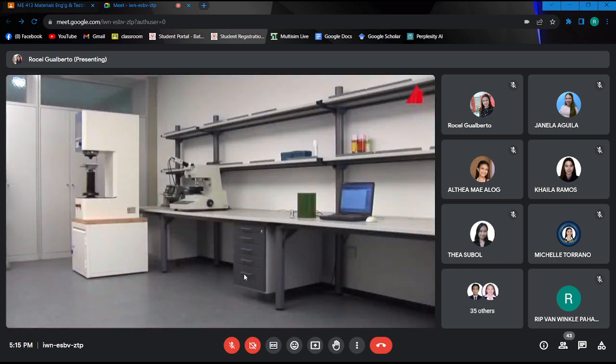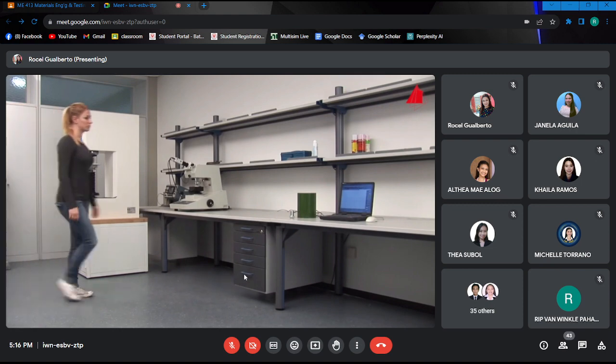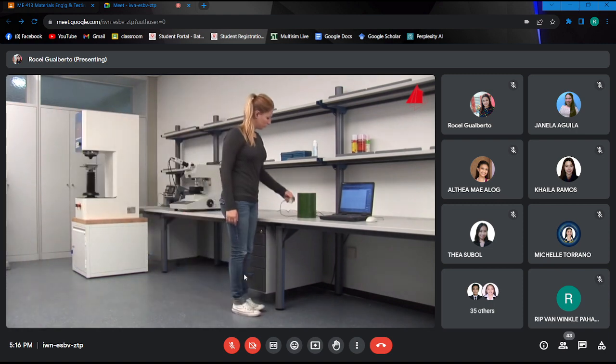In our laboratory, there's a green painted steel cylinder to be found. It contains artificial defects which are invisible from the outside. To track down the defects, the material tester uses the pulse echo method.